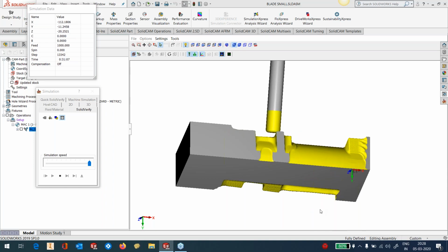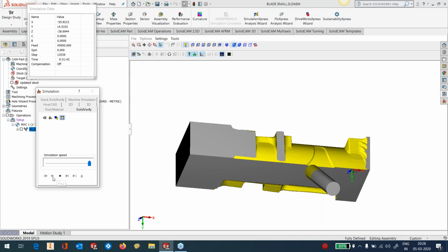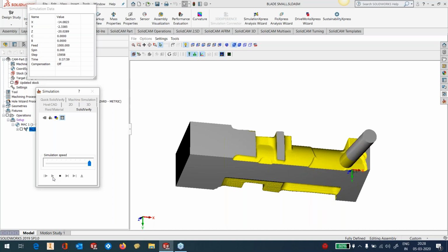So any part rotating around X or Y is a candidate for screw machining. In fact, like I said, we need to change the name of the whole technology, and I'm just putting forward my idea that we call this rotary roughing, because you could perhaps machine anything in 4-axis with this particular function.